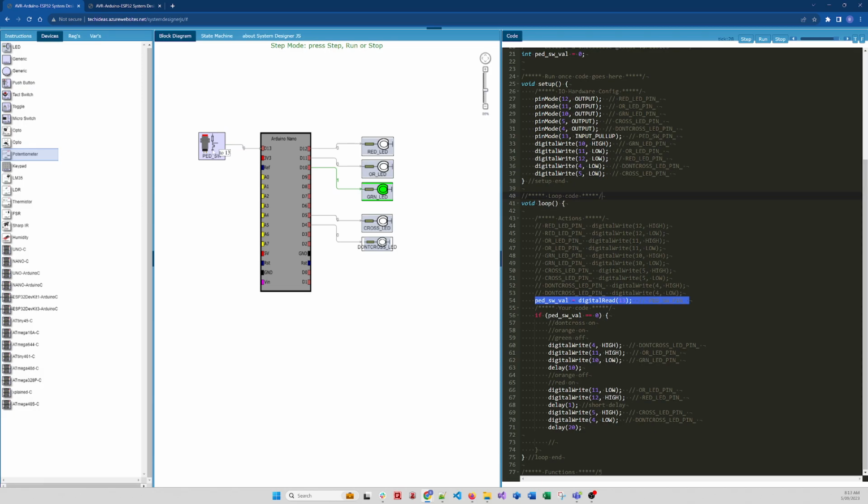And when we press it, it goes to 0. And we use this reverse logic, okay, in computing with microcontrollers and embedded systems. It's pretty common to use it this way so that when we press it, it goes to 0, and when we release it, it goes to 1, okay? And as you can see here, the LEDs are off except for this one, which is a logic 1, and the LED is on, okay?